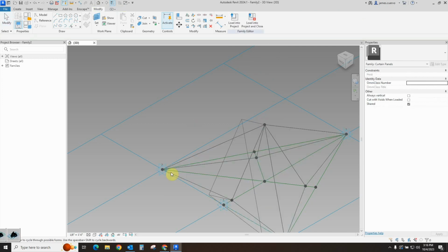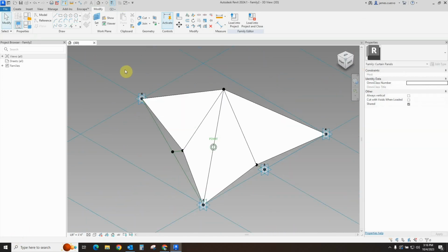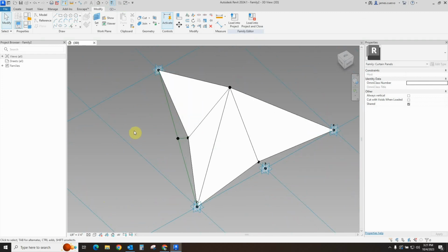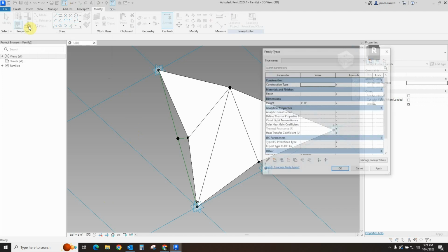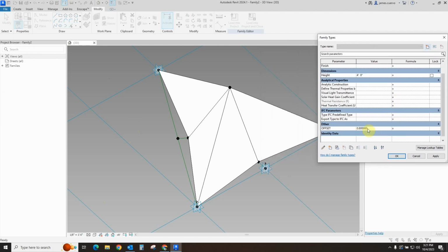And create our surface, flat surface as we wanted it. And there is our item. And the way we make sure that this is working properly before we actually bring it into a massing family type to test it completely is we go to the family types here, open that up. Let's go to the offset, which is the one that we have made that is a bit more easy to manipulate because it's an offset value that controls these distances.